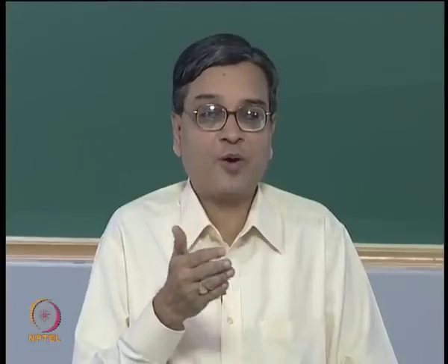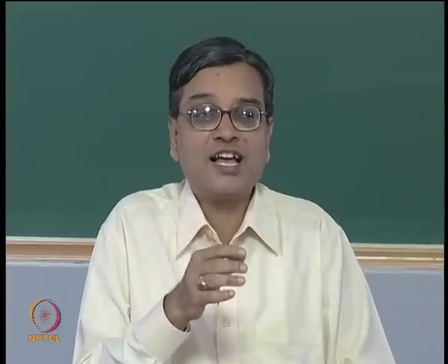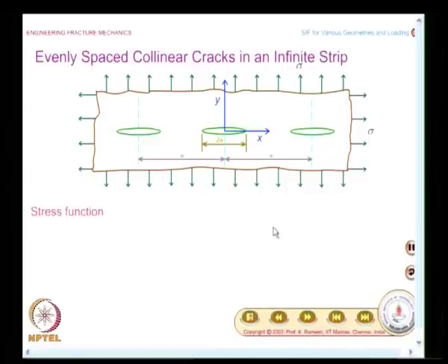Later I will solve the problem by a method of superposition. There you will again get the same answer. The reason is, for you to appreciate method of superposition, this answer will give you some kind of a confidence, because you have already seen the result is p naught root pi a. I am going to get the same result by method of superposition. So, you learn the nuances of method of superposition from this result, then apply or extend method of superposition for other class of problems. And as I mentioned earlier,